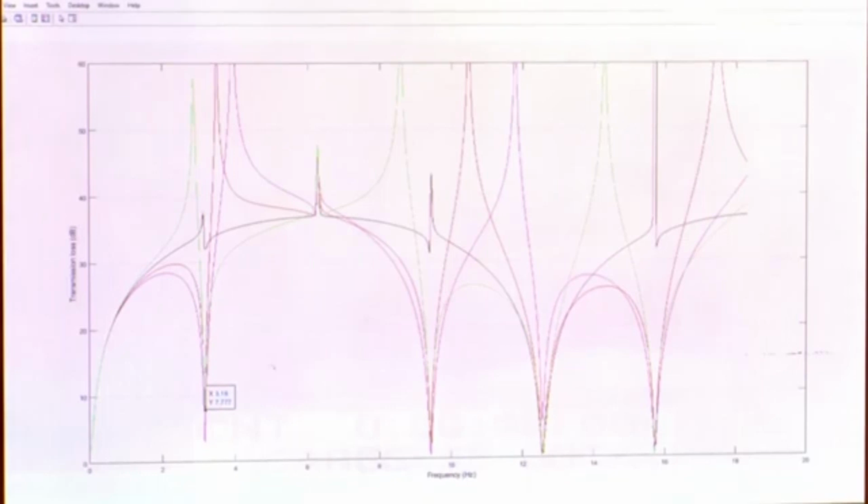That is why it is very important to tune it to match the trough at the first axial resonance, and then we will be able to completely eliminate the trough at the first axial resonance peak. So, by choosing the extension at the inlet L1 equal to L by 2, we are able to completely annihilate the trough that would otherwise occur if the extension was not tuned. And similar logic applies for the extension at the outlet, that is at this point.